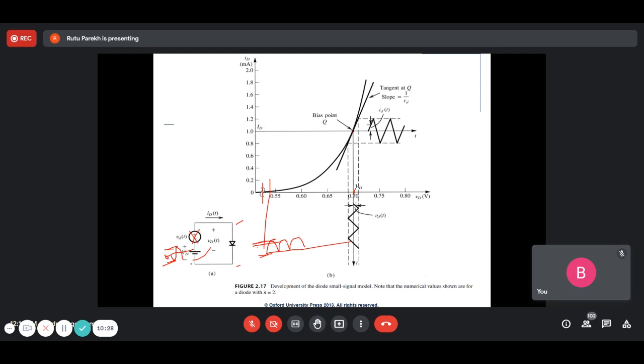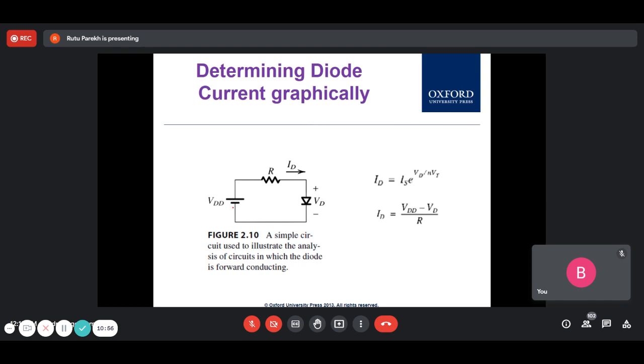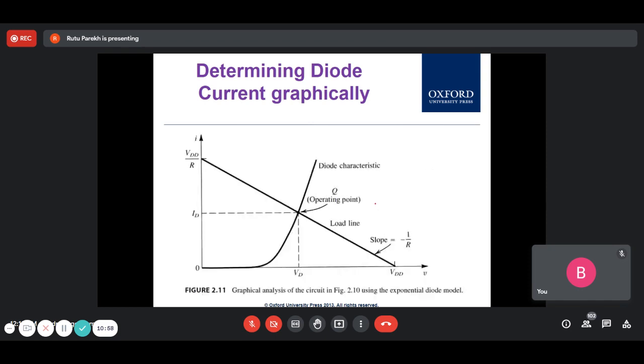So do you understand two different applications? When it's already high voltage, you don't have to give bias. But analog circuits are to process very weak signals. Diode application is rectification also, where you don't have to bias it. But when you are processing weak signals, which is usually the case, in any embedded application there are sensors and the circuit is to process that.